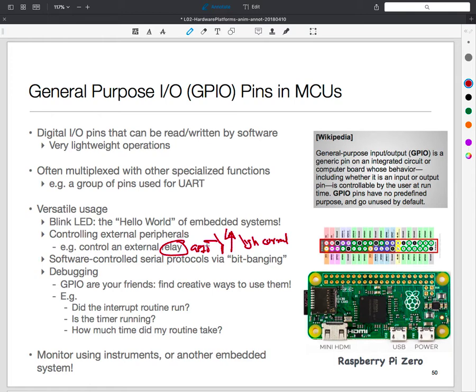For example, it could be controlling your pool motor, which is 240 volt AC actually. So it could be either high voltage or high current, and then your little device, like your Arduino or whatever, may be connected to this guy. Now, doing this would actually be fairly risky. Why would it be a bad idea for me to control pool motor voltage out here and my little GPIO sitting out here?